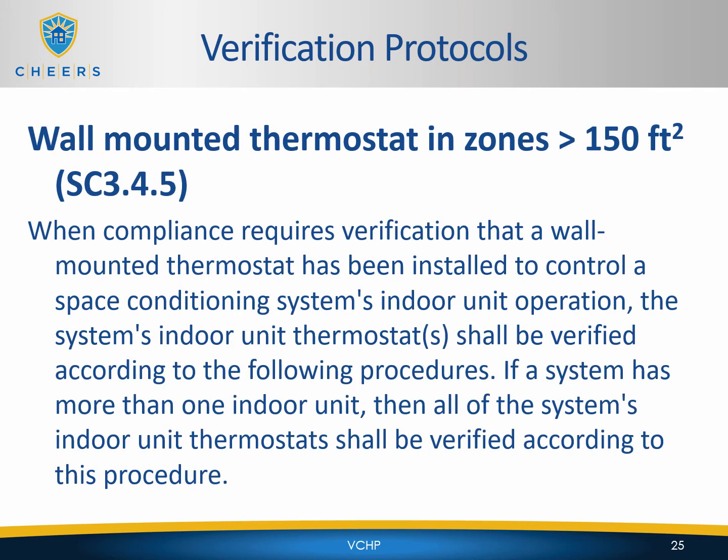When compliance requires verification that a wall-mounted thermostat has been installed to control a space conditioning system's indoor unit operation, the system's indoor unit thermostat shall be verified according to the following procedures. If a system has more than one indoor unit, then all of the system's indoor unit thermostats shall be verified according to this procedure.